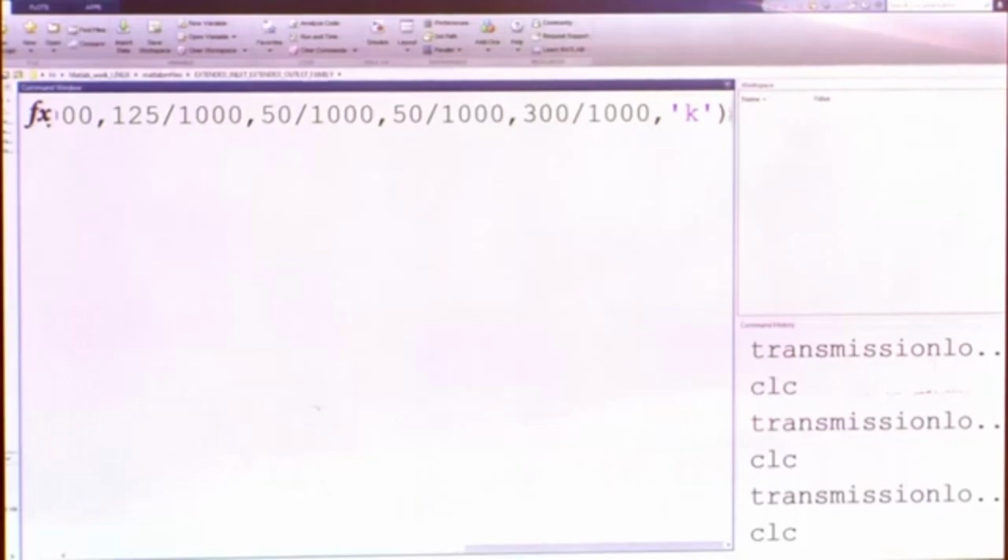The maximum diameters used in commercial automobile mufflers is about 300 mm or so. In some cases it might go up to 325, 350 mm, and it ranges from 150, 175 all the way up to 350 mm.